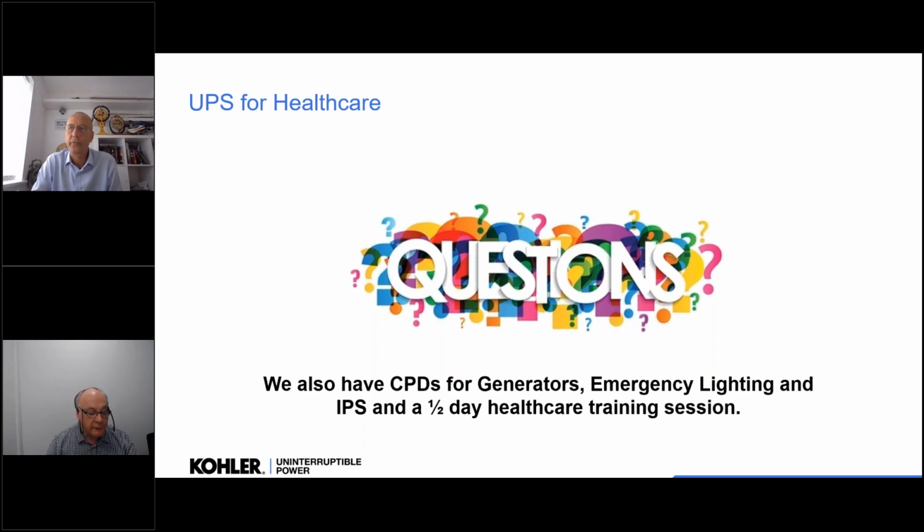Thank you. Somebody else has asked, how often does a hospital UPS need servicing, and concisely what's actually involved when that occurs? Okay, the UPS, according to the guidelines and from us, to be honest, we like to maintain the UPS twice a year. It should, however, be checked on as often as possible. I think HTM says minimum monthly to make sure that it's available.